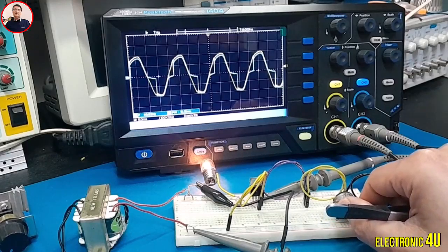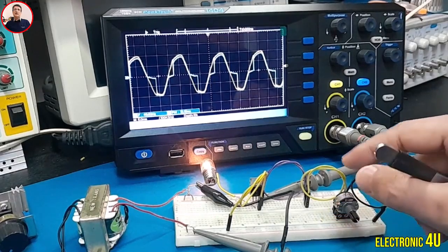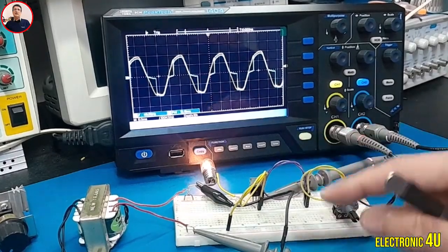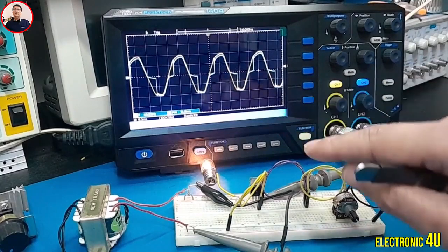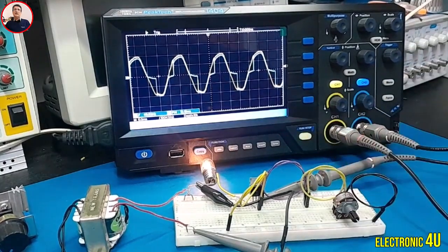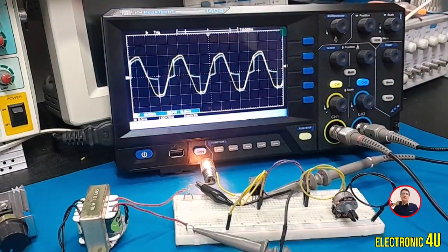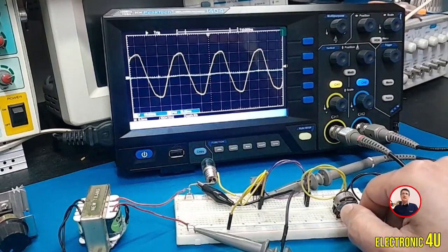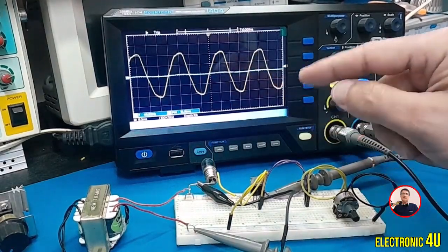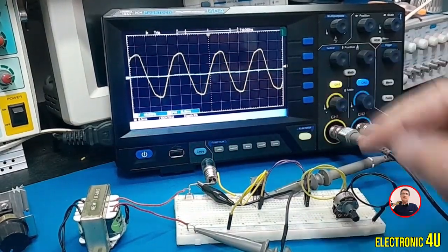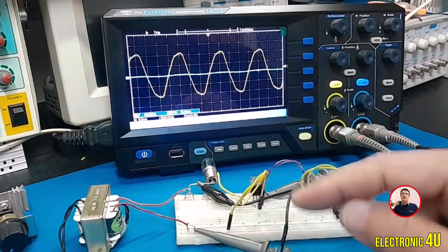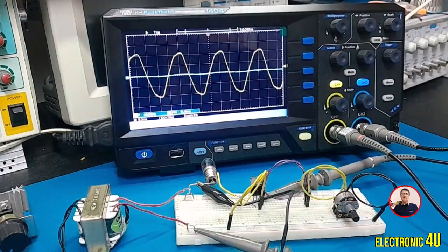This is a larger firing angle, for example, close to 90 degrees or even more. At a 90-degree firing angle, the Triac activates in the middle of the half cycle, and only the second half of the half cycle is delivered to the load. And if we could bring the firing angle to 180 degrees, the Triac would activate at the very end of the half cycle, or basically not activate at all, and practically no voltage would be transferred to the load, and the lamp would be off.